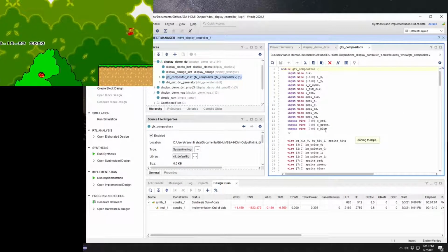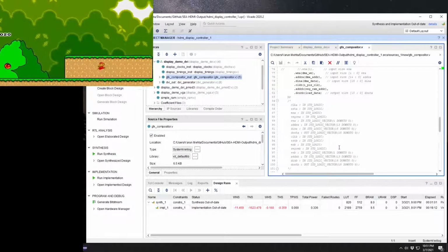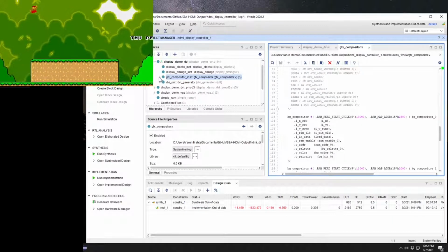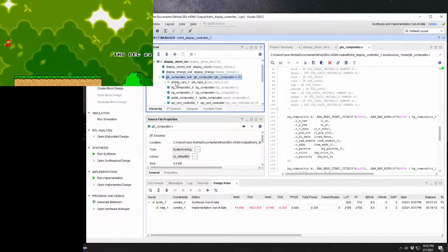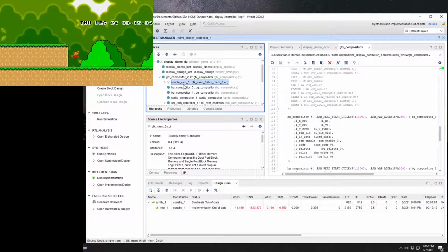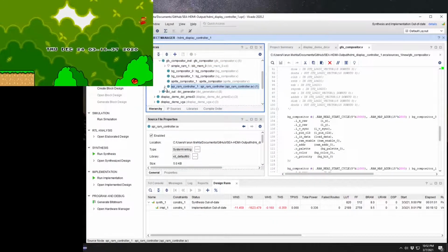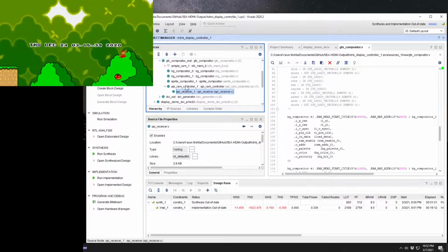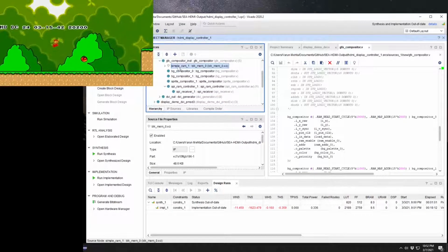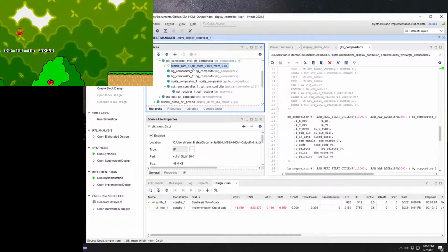The graphics compositor is where we start to see some changes. So like I said, the drawing side of this is really hardly different, but what has changed is if we follow this hierarchy down, you'll see the graphics compositor now has a RAM, its RAM component. The IP for that is changed a little bit. And then there's another component here, a SPI RAM controller and a SPI receiver. These are both components that I designed myself, and the simple RAM is still the standard Xilinx IP for block RAM.